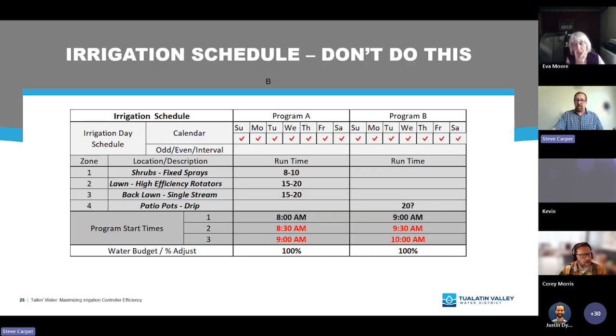And the next thing you know, you've got multiple start times. This is an extreme example, but I have seen cases where every one of them is filled out. Then you measure the flow rate on each zone, you do the math for them, and you illustrate pretty quickly how, yes, you did use that much water. Don't feel bad. It happens, but we can help you adjust your way out of that situation.